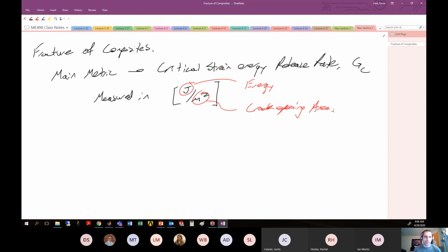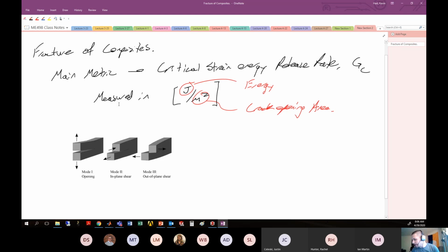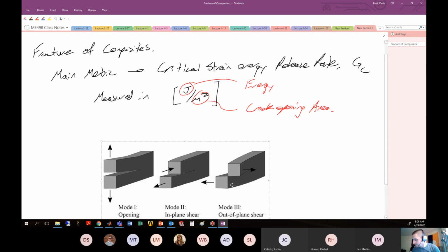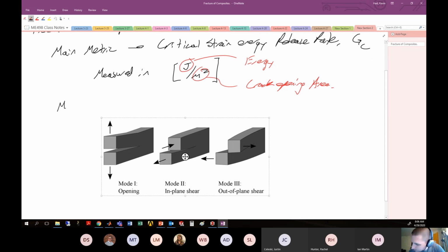We looked at the different modes of fracture. So I drew for you those modes of fracture. We talked about those. I'll just bring this picture in again to reinforce that you have these three different types of fracture. That is mode 1, this Pac-Man mode. Mode 2 is in-plane shear. So that's like your deck of cards example. I wanted to bring a deck of cards in, but I forgot. So you have these layers, and when you put some load on them, they slide against each other. So that's this in-plane shear. The loads are in the same direction as the crack propagation.